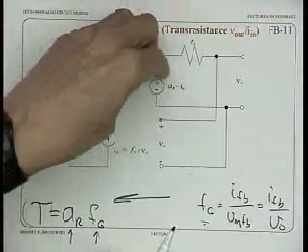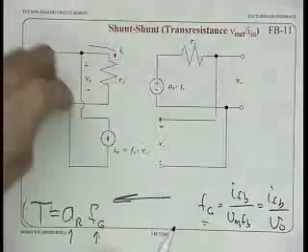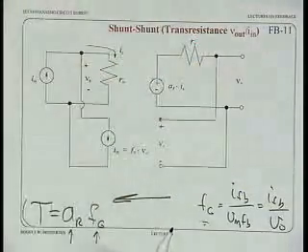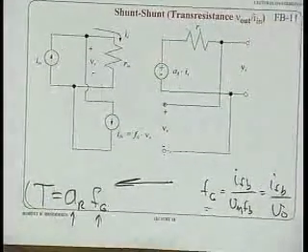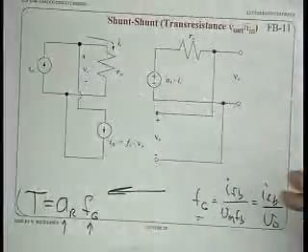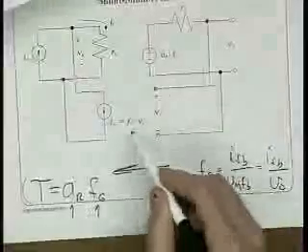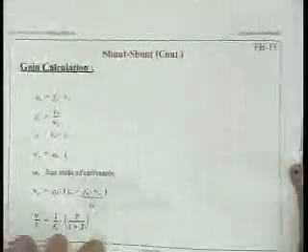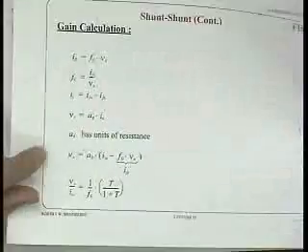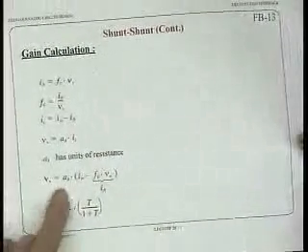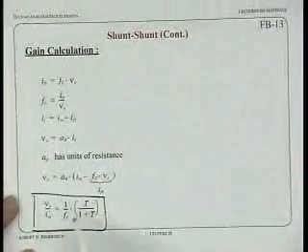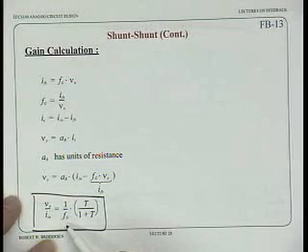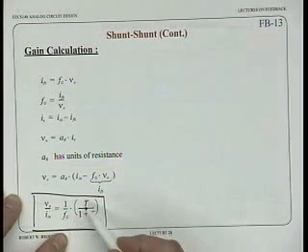So you have a transresistance amplifier and a transconductance amplifier. In the loop, if you go around the whole loop, then you end up with a unitless situation. Okay? So let's take this. We write our little formulas. I feedback equals Fg times Vo. F is our feedback factor. Fg equals, and so on. I error is equal to the difference of the two currents. Going on and on. V out equals this. And you end up with V out over I in equals this. 1 over Fg. Fg is the transconductance feedback factor times T over 1 plus T.